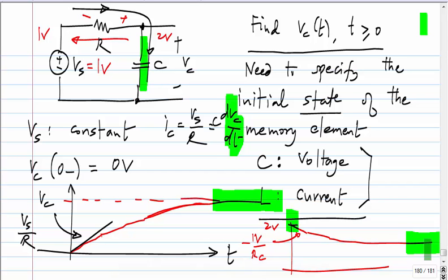So, actually there are two parts to solving for circuits like this: the part that depends on the initial condition and the part that depends only on the input. Okay. Those are known as transient and steady state solutions, and we will look at those things as well. Okay. So, every circuit with capacitors and inductors, with memory elements, will have these properties. Depending on the initial memory, it will have something, and then finally the effect of memory will die away, just like you have forgotten what I taught in the first week. So, you will only react to what is happening right now. Okay. So, it will only depend on the inputs that are applied. Okay.